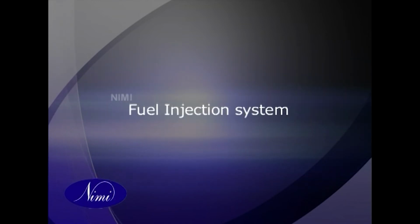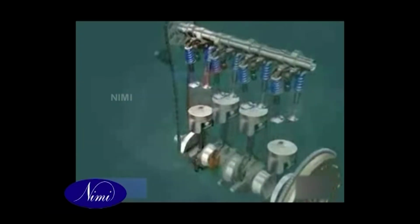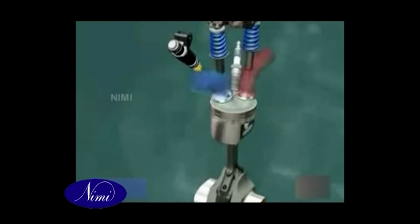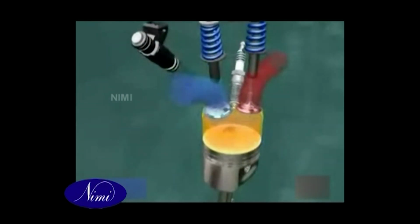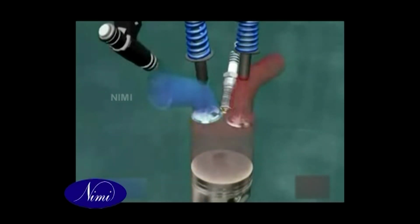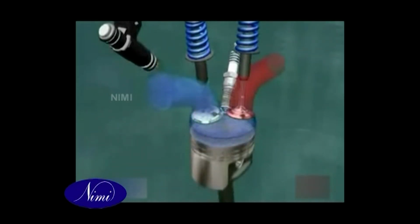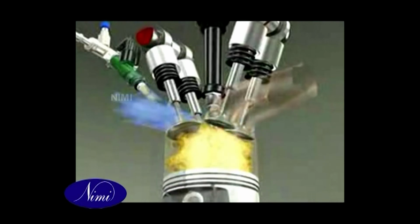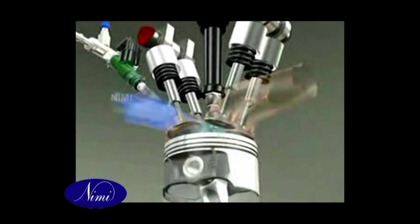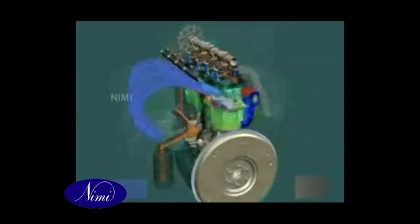Fuel injection system. The engine demands that the fuel supplied is: 1. Timed to inject when the piston is near the end of the compression stroke. 2. Atomized, broken up into fine particles. 3. Forced with sufficient pressure into the hot, dense, turbulent air. If these demands are not met, the engine will knock excessively and the exhaust will be dirty.